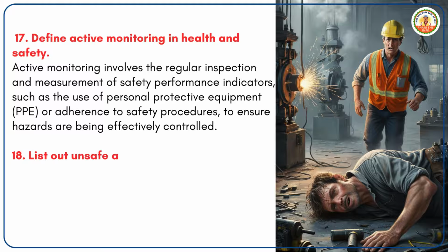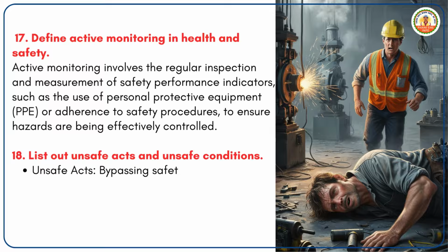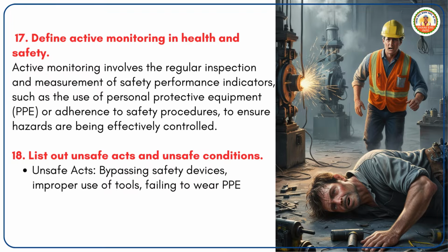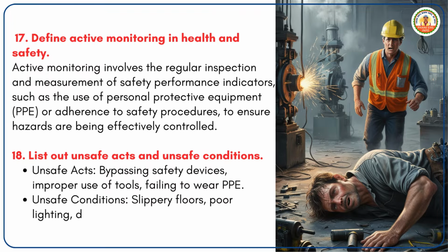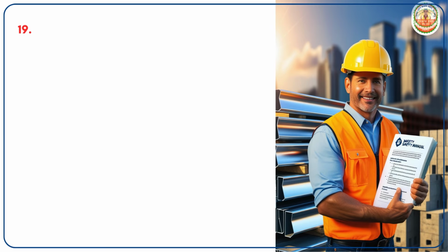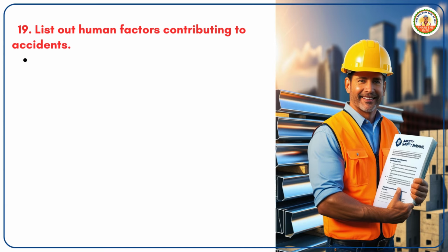18. List out unsafe acts and unsafe conditions. Unsafe acts: bypassing safety devices, improper use of tools, failing to wear PPE. Unsafe conditions: slippery floors, poor lighting, defective machinery. 19. List out human factors contributing to accidents.